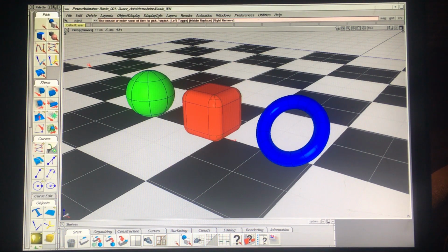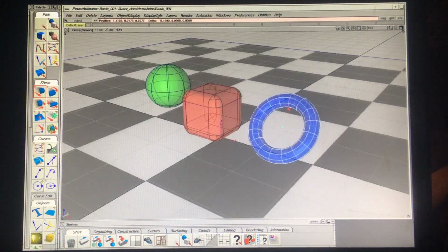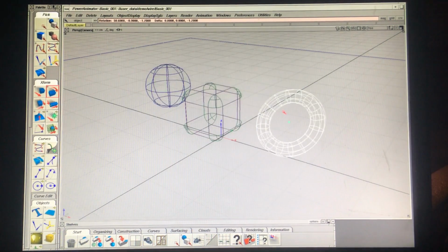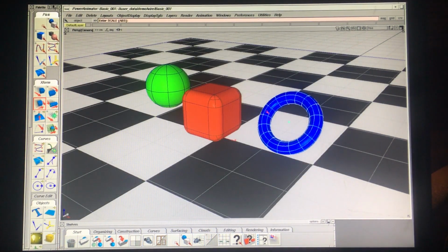So Control Q, and then Shift Q. Oh yeah, so now I can do picking things, unpicking things. Okay, let's pick, and now, yeah, round group, here, toggle. Okay, that's working. Now if I go Shift W, oh yeah. Now I can move like this and like this. Shift E for rotation. Yeah, that's working. And Shift R for scale. Yeah, that's a lot better. And then we go Control Q for nothing and Shift Q for pick.